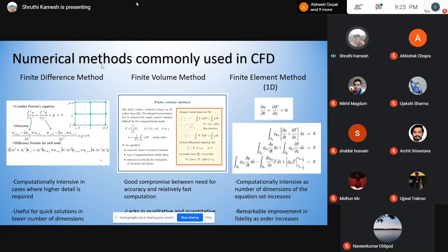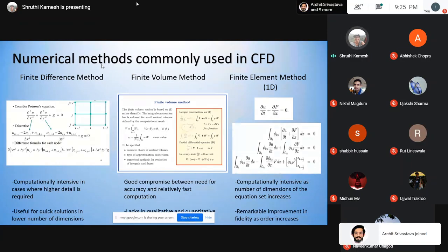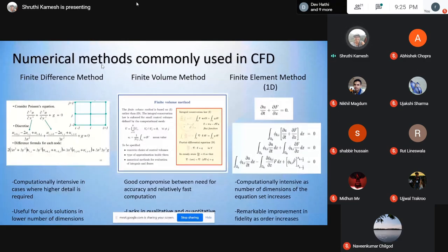So what I mean is that, given a particular mesh, this is a nodal solution, finite element. Finite volume is just sort of a deconstruction of that, but finite element solves for the values at the nodes in the I, J, K dimensions. So phi ki refers to the weighting function value at the kth node of the ith element, so to speak.